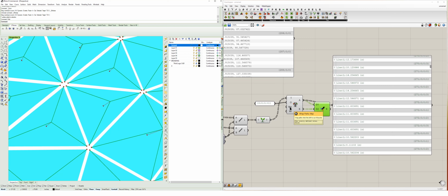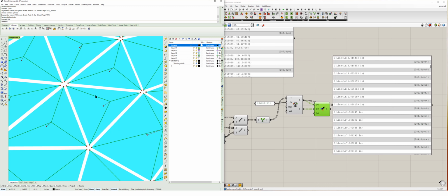And then we also want to go to wrap paths and set that Boolean to true, because we have a self-contained loop within each space frame. So essentially what that's doing is putting this line with that line, and then that line with this line with that line. And so each of them are grouped together on their own branch. And if we hadn't done that wrapping, it would have missed one of those panels at the end.